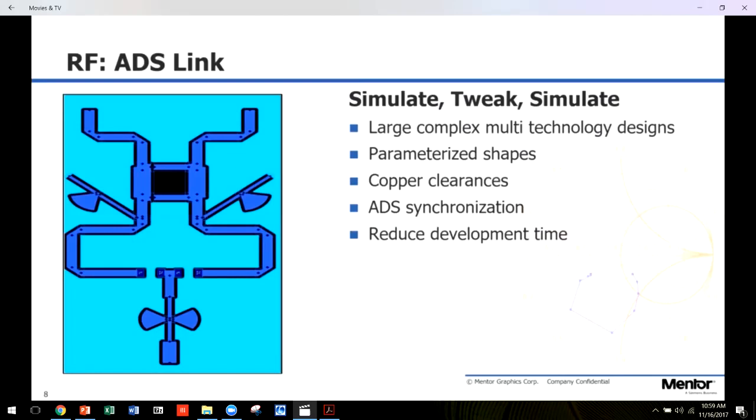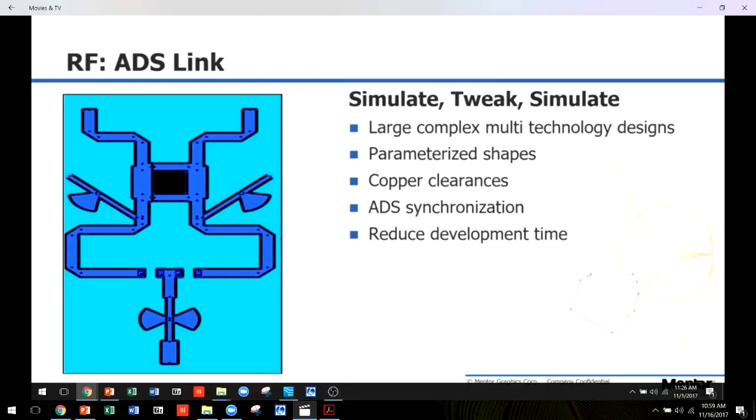Use a tool that understands that physical connections are not always a short circuit, contains smart clearances, and parametric descriptions that can be simulated. Don't manually export or import Gerber for simulation. The built-in synchronization wizard directly translates your RF design into Agilent ADS or National Instruments AWR, saving critical setup and processing time. This allows faster design iterations by changing, checking results, and changing again.